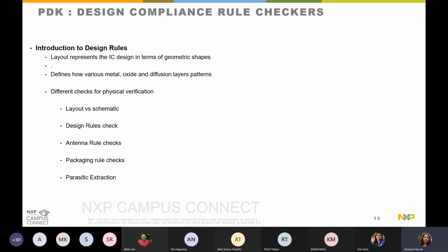Likewise, packaging and parasitic extraction models are available. These models tell what the extracted output would be, and whether those parasitics are okay for the device performance, or whether we are going beyond the performance specs. Likewise, for the DFM part, design for manufacturability rule decks also decide how manufacturable the design will be, and these rules help get more process-friendly layouts done.